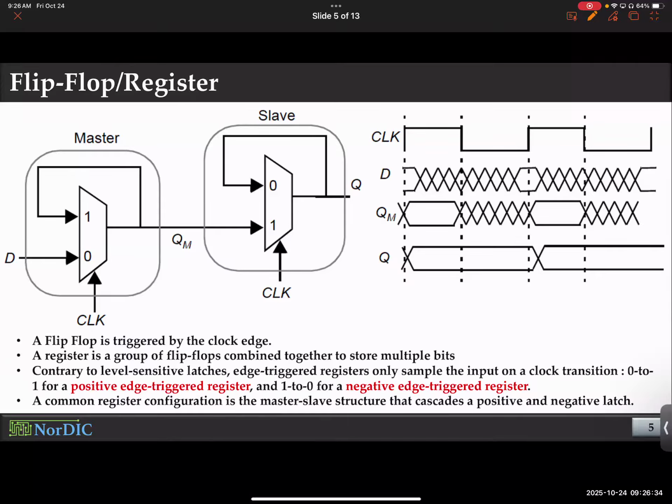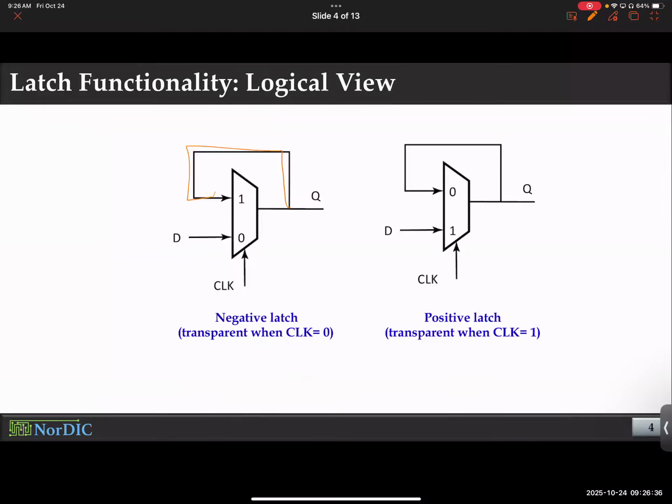What I'm trying to allude to is that even though it's a super simple modification to a conventional combinational circuit, you basically create something called a memory. You create the concept of the memory for the first time. No other logic gate had memory, because the moment an input changes, the output will change right away. They were so sensitive, but memories cannot do that. Memories have to hold on to the data, even if something changes here and there, unless there is a control signal that changes and lets you change the memory. Keep that in mind.